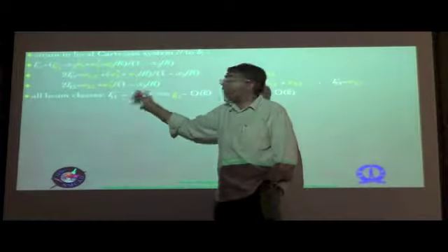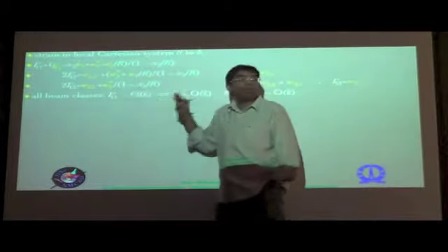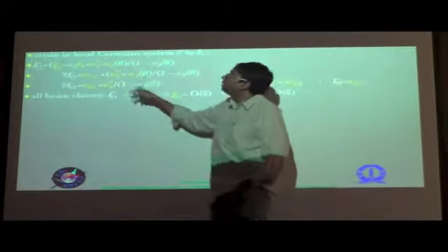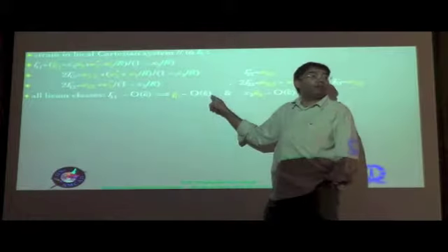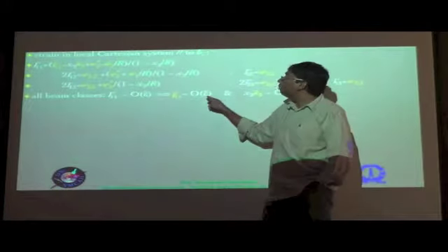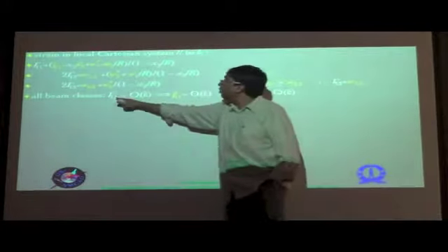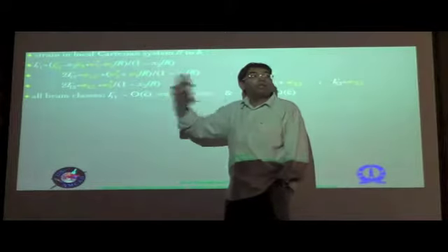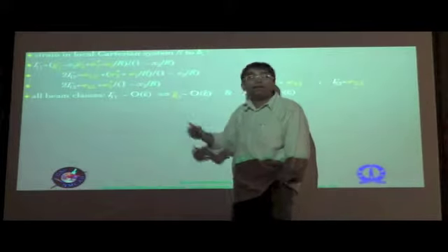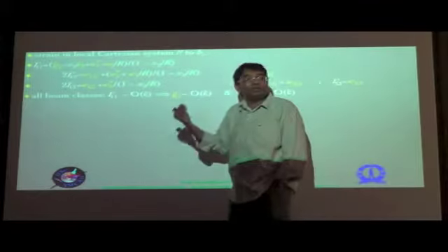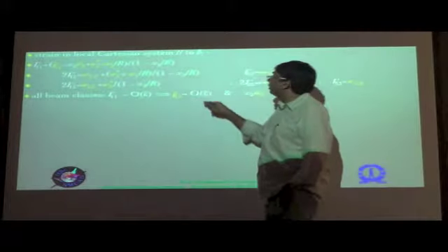That's what this particular mathematical expression means, okay? So now what that in turn means is that your gamma 11 bar should be of the order of epsilon hat, because if this were bigger than epsilon hat, then your gamma 11 would be bigger than epsilon hat. One of the strain components would be bigger than epsilon hat, or in other words, you would have reached failure of the material. So that is quite obvious.